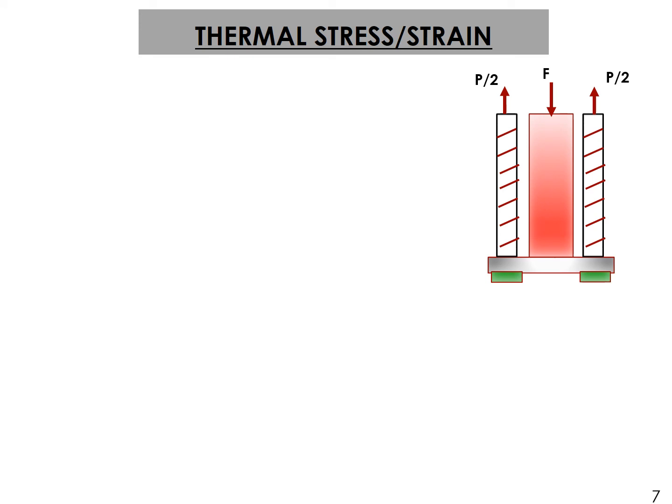Now I have taken finally the forces acting here. As it is clear, because there will be a push, this mechanical force is required here to push back the thermal displacement so that the equilibrium is maintained. It is being done by the supports. Now supports are able to do their work because of the tensile force acting in these bolts.